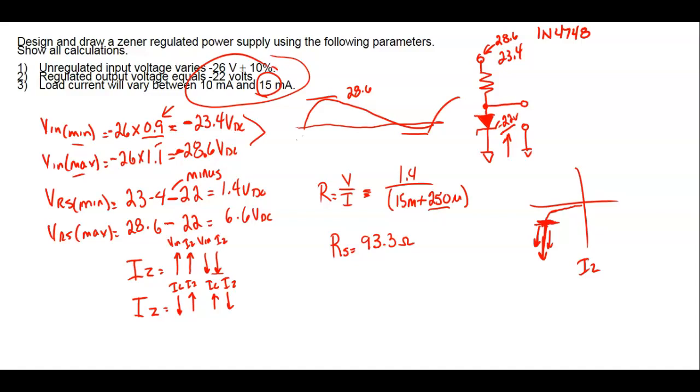So inside that data book, there should be a chart that gives us the standard resistor sizes. So I see 93.3, and what's the closest standard resistor going down, not going up? We're never going to round this up. We're always going to go down, right? So what's the next standard resistor size below? 5%, yeah. That's all we're going to use, fellas. What's that? 91 ohm, right?